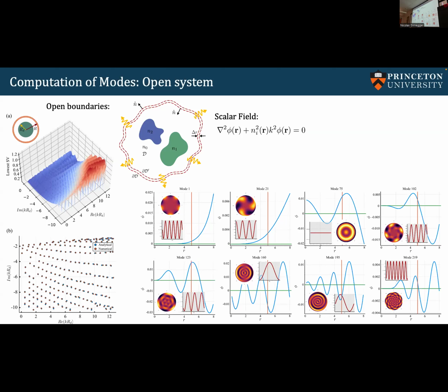And here we propose one approach to implement open boundaries, because you want to contain your simulation model to just a finite boundary. Because of course you have limited simulation resources. And the idea is that we'd like to limit it to be as tight as possible. So an imaginary boundary that contains all the components of the circuit and nothing else. And it sounds a lot easier than it actually is, because we typically don't know the radiative profile escaping an arbitrarily shaped boundary.